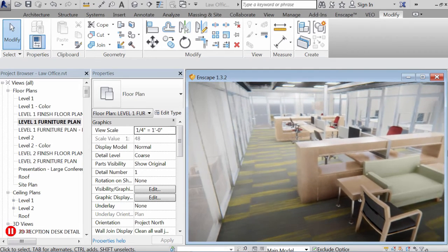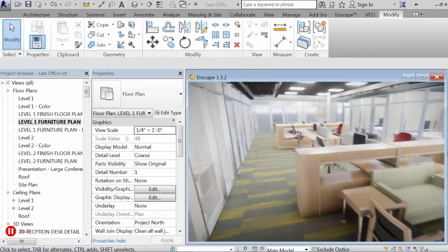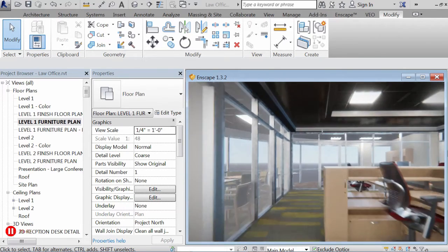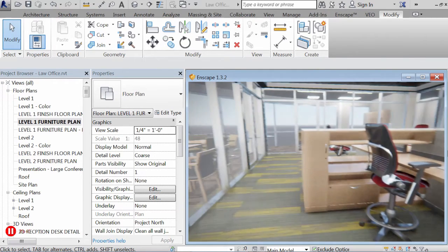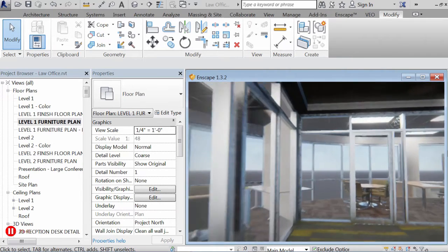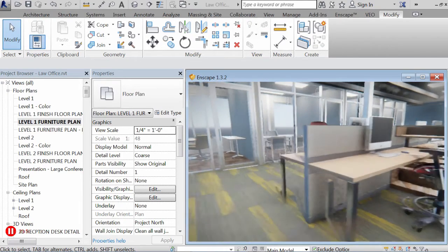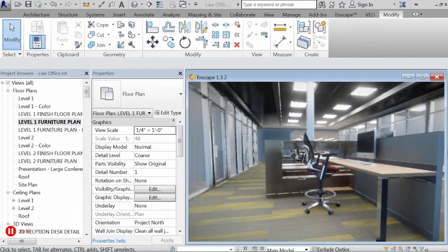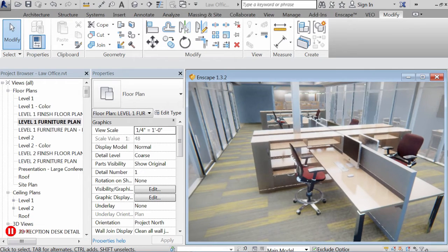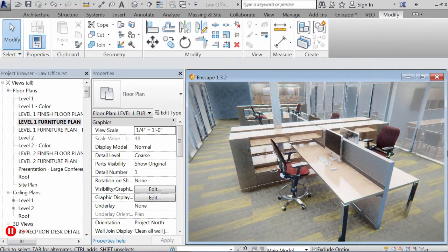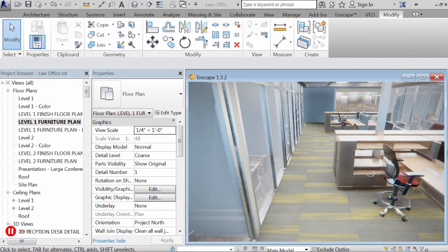One of the challenges that I mentioned in the book when you download manufacturer content is, and this is just the way Revit's designed, that the textures don't come along for the ride. When you download an RFA family, you don't also get the textures embedded in that family, right? And when you do renderings, you get errors saying that these textures are missing. So you really need to find on that manufacturer website, which they usually have like a zip file, you can download all the JPEGs and PNG files. And then in the Revit options dialog box, you can do the material mapping so that Revit, and I presume Enscape, knows where to look for those materials.